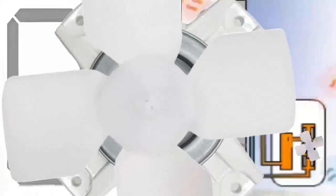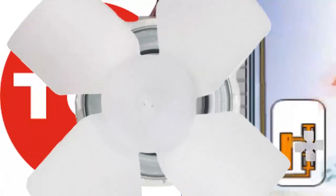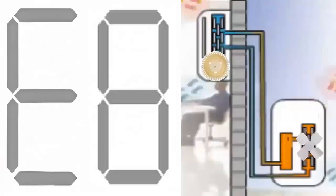4. Verify the cleanliness of the fan and coil of the outdoor unit to ensure that the equipment is in optimal condition. Remember to visually check the correct rotation of the fan with the unit turned off. Make sure the fan blades rotate freely to rule out mechanical problems.